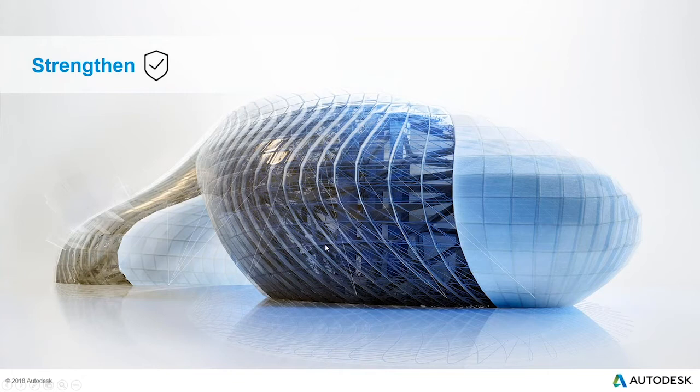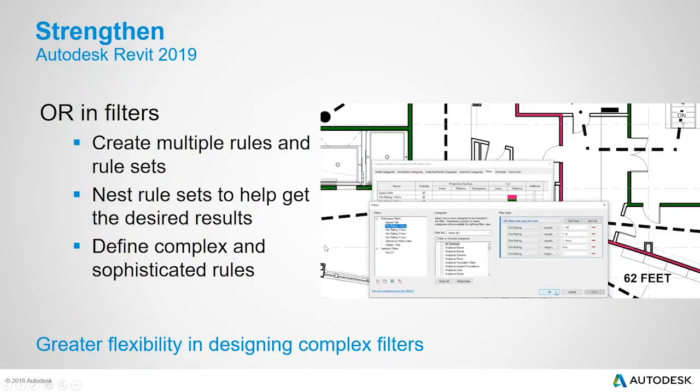Next, we're going to talk a little bit about functionality within Revit 2018 that has been strengthened. Filters now allow you to query your model for information based on one or more user-defined criteria. Filters are structured such that the results yield yes or no answers. In situations where you want to create a more complex query, you can string together more than one question.